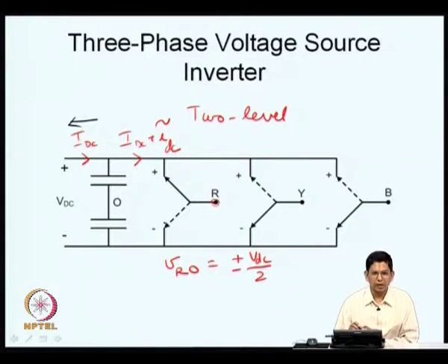It is actually a bidirectional converter, power can flow in either direction, that is the point that I would like to make now. This is called a voltage source inverter because you can apply a certain voltage at this pole irrespective of the direction of current that is flowing through. The current can be in both the directions. This is what we took into account while designing the switches.